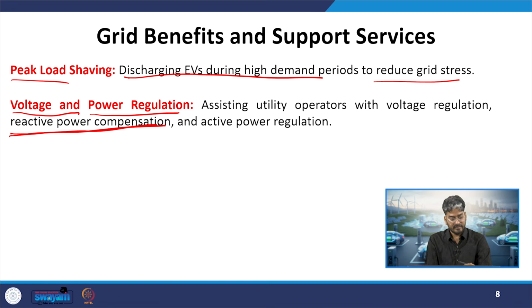So, that can be done irrespective of the mode of the vehicle, that is irrespective of our active power. That is what we have seen. Both active and reactive power are perfectly decoupled, because generally we use our DQ frame control, or the decoupled current controller, where our active and reactive power can be independently controlled.